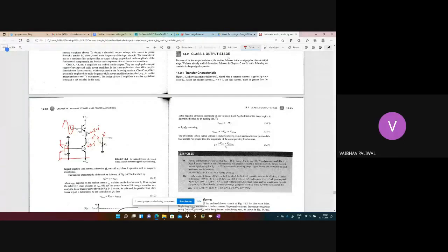Okay, sir. So what happens, this signal gets transferred to output in same phase. To make you understand more, Q1 is acting as nothing but emitter follower or the common collector amplifier, of which the voltage gain AV is unity, right?